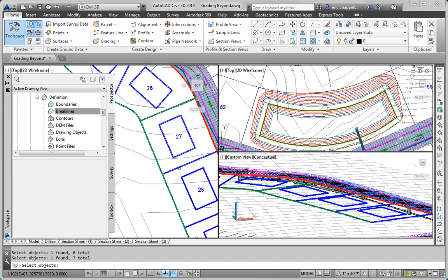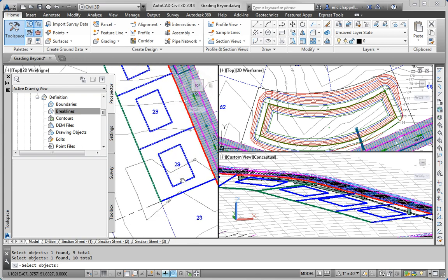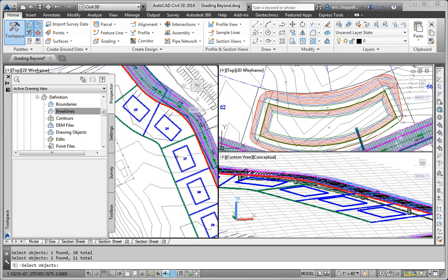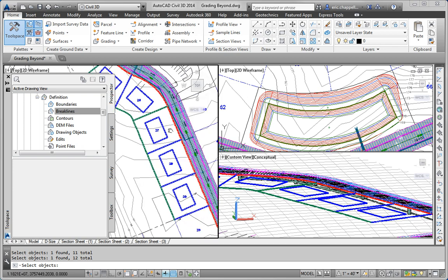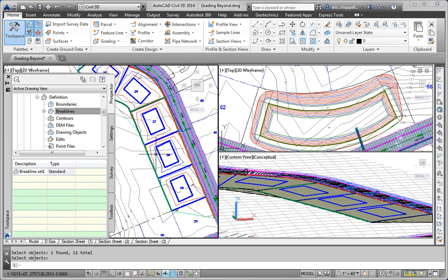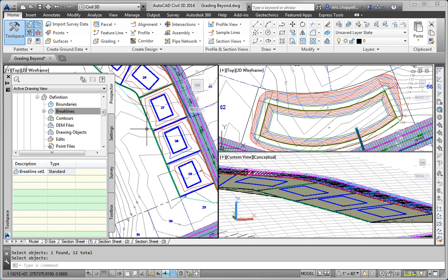While I'm picking these lines, I'm also thinking I'm going to need to supplement these lines a little bit because, especially these lot lines from front to back, there's not a whole lot of data points on them. There's only two, in fact, one here and one here. The building pads only have, I think, maybe 6 or 8 data points, so there's not a whole lot of points there to define a surface with. And I want to make sure I pick the road feature line as well. So those are all my feature lines. And that actually looks pretty good. I didn't do any supplementing or weeding.